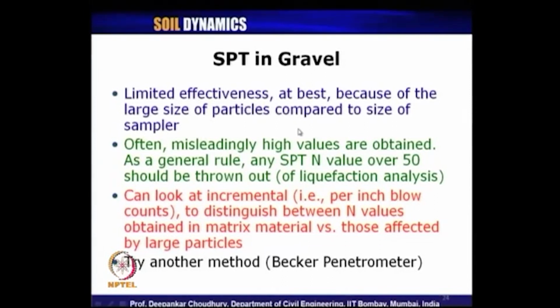So, what is mentioned mostly for gravels is that we should try another method, which is called the Becker penetrometer test or BPT. Standard penetration test is good for sandy type of soil, whereas BPT is good for gravelly type of soil. So, with this we will complete today's lecture. We will continue our lecture in the next class.